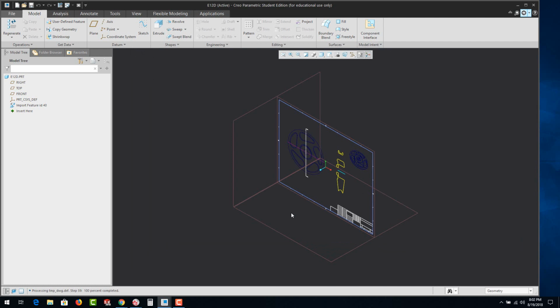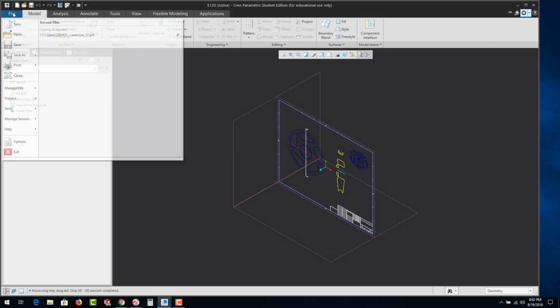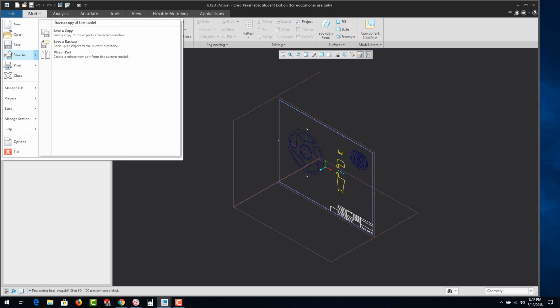And then another thing, when you're importing these types of files, it's not a bad idea to increase the actual precision of the document. What I've discovered when I've had it set on low precision, there's gaps sometimes that it seems as though it's caused. And that actually may not be Creo's fault so much as it was the legacy data that when it was created in the old CAD system, wherever it came from. That might be an issue.